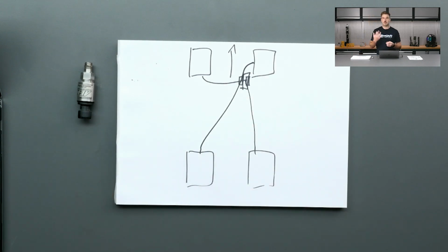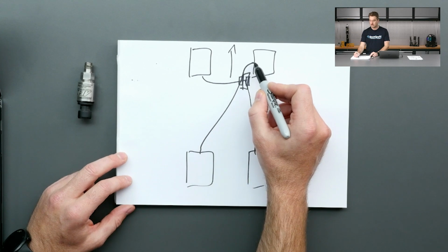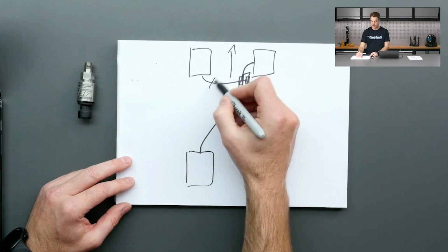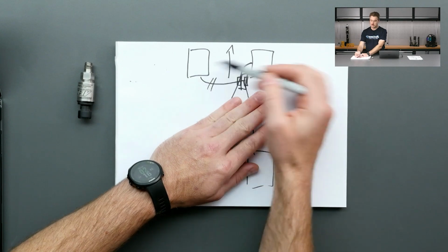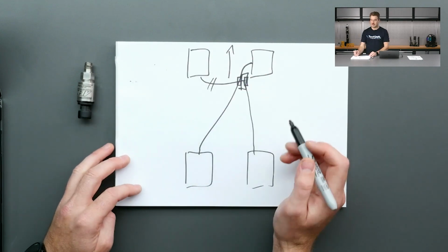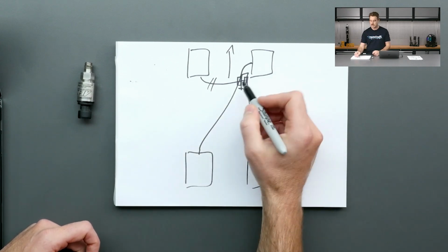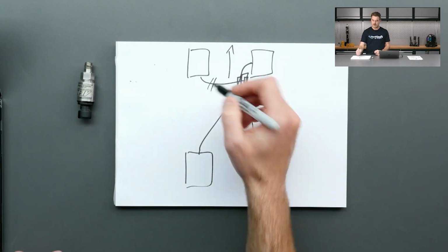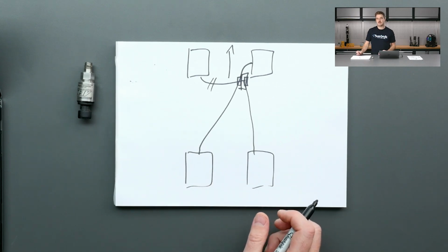Now obviously they've got different pressure ratios and different pressure sources out of the master cylinder, but the reason some manufacturers do this is because, in the event you have a hydraulic leak, a brake line failure or something like that, say one of these hoses is gone, if the brake pressure system was plumbed with the front and rear separately and one of those fronts went, you'd essentially have no front braking. But if you split them diagonally like this, then at least if you have a failure in one of those diagonal circuits, you've still got one front brake left to do the braking for you.